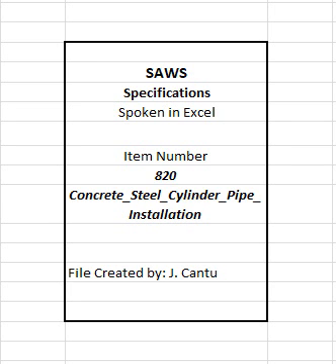Such payment shall also include excavation, selected embedment material, backfill, compaction testing, polyethylene sleeve, hauling and disposition of surplus excavated material, including all existing pipe, fittings, appurtenances to be abandoned or removed, installation of all-weather surface, and other required testing as per Specification Item Number 804, Excavation, Trenching and Backfill. 2. Materials paid on site will be in accordance with Table 1 of Specification Item Number 100, Mobilization.